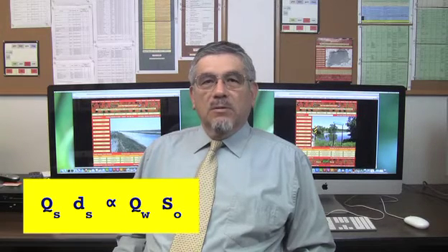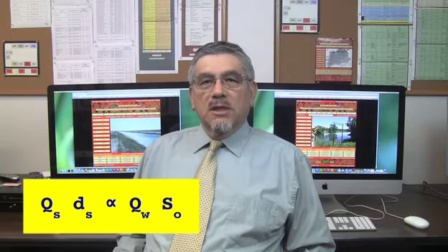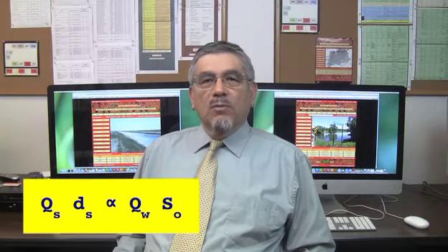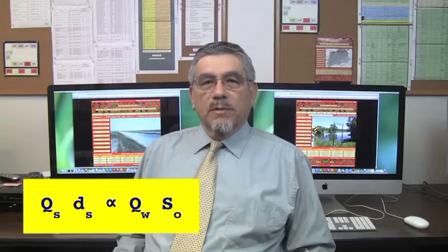Under non-equilibrium conditions, when any of these variables changes, the relation indicates the direction of the changes which are necessary in one or more of the other variables to restore equilibrium. For instance, if the sediment load is decreased, equilibrium can be restored by decreasing the water discharge or the bottom slope, or by increasing the sediment size.